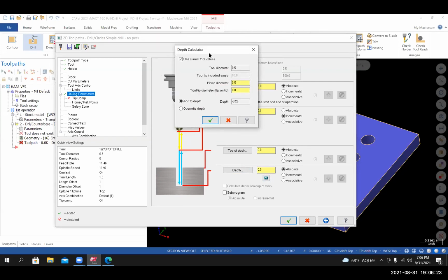We're going to create a pilot. And what I mean by a pilot, it's a conical profile left by the drill. The diameter of the profile is going to be equal to the diameter of the hole that's being drilled in the part. I don't want to drill too deep because I can make a countersink, or I can make the hole out of tolerance. I'm going to set my finish diameter equal to the hole diameter, 0.201.